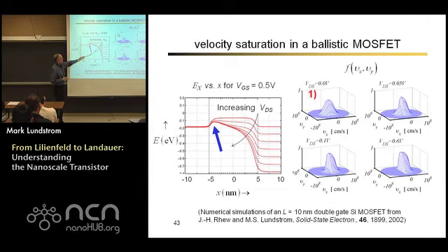Okay. Now you apply a little bit of gate voltage or drain voltage. You lower the Fermi energy, you lower the conduction band in the drain. Okay. No problem. The positive half can still come in. It's just like it was before. The negative half, though, has to hop over a bigger barrier to get here to the virtual source. That means fewer of them are going to be able to hop over. The negative half is smaller. That means the average velocity now is bigger than 0. Current is flowing.